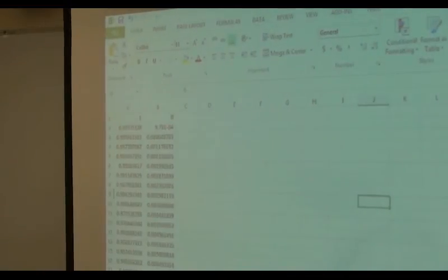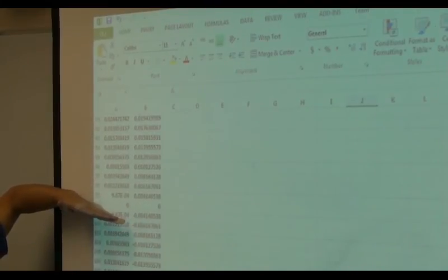Well, we still have a problem. What kind of problem is that? Let's take a closer look at the data structure here. This is 1 and 0, the trailing edge. These are positive values, from here to location 0, 0, which is the leading edge. So this chunk is upper surface data. This is the leading edge. This is a minus value, so this chunk is lower surface data.